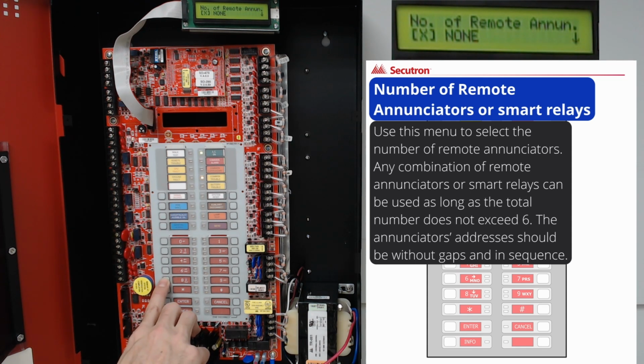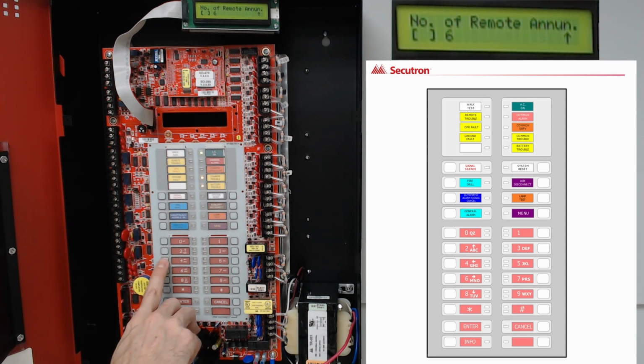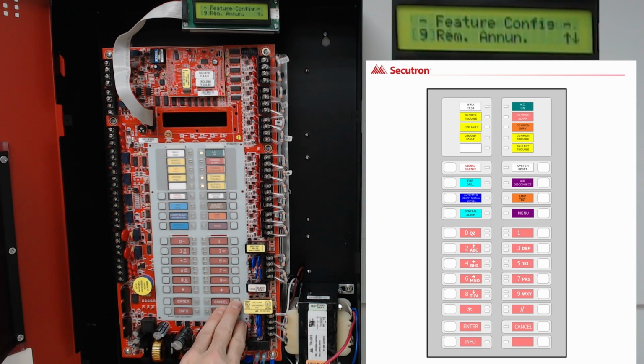We can hit the down cursor arrow to select 1, 2, 3, 4, 5, or 6 remote annunciators or smart relays. When we see the desired number of remote annunciators or smart relays, we hit the left or right cursor arrow to apply the X, hit Enter, and then exit by pressing Cancel. Back out to the previous menu options.